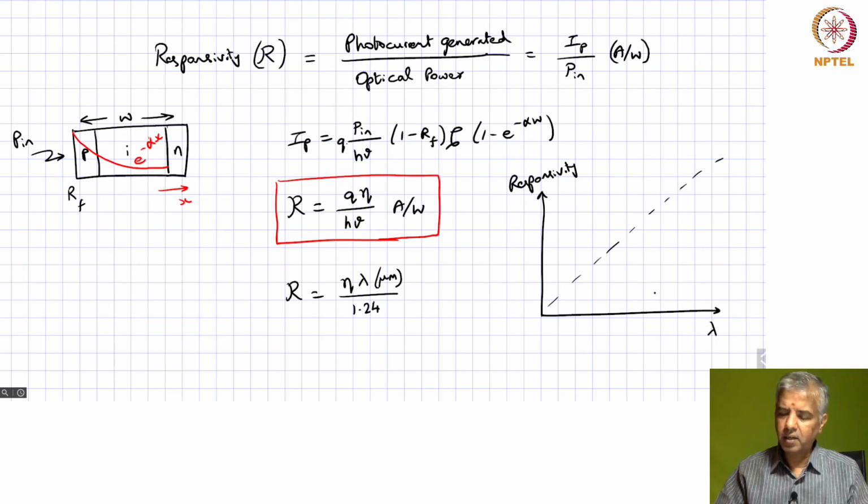But like I said, R cannot be arbitrarily large, because as you increase in wavelength, your frequency is decreasing, and h nu, the energy of the photon, is decreasing, and there comes a point where h nu is less than the band gap energy, okay, and in that case you cannot have any absorption happening within this structure, right? So that corresponds to this point over here.